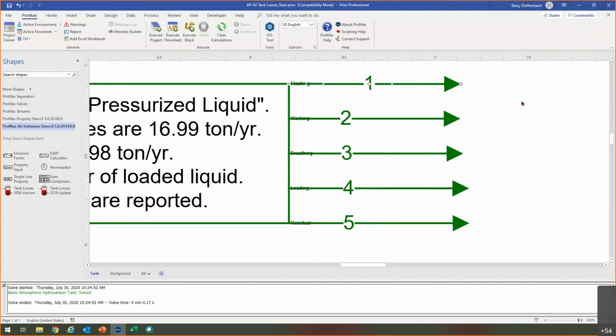It does give it in terms of hourly emissions, I believe. The modifications to it are estimates. In AP-42, it does explicitly say that you shouldn't be using AP-42 calculations for anything less than a month. But there's estimations from TCEQ on the short-term worst case, and that's typically worst case loading is what it's based off of.